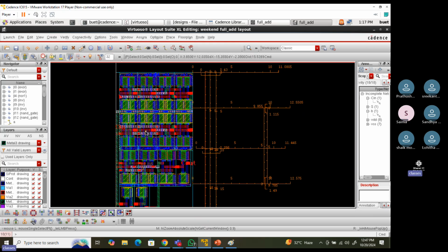Yes, that is actually required, and I did it as per the situation. Suppose an M2 metal is there, and I have to connect another M2 metal. But I cannot directly draw an M3 because an M3 in the middle is there, or another signal is. In that case, you have to use M3 and then jump using an M4 metal, because two M2s are there and one M3 is in between. Suppose the test case is like this.